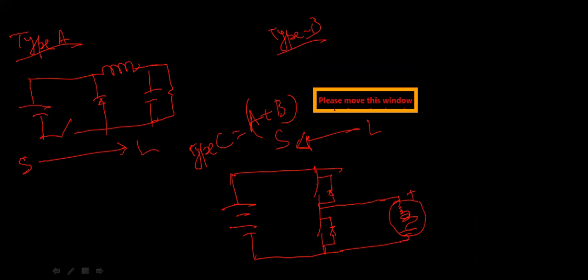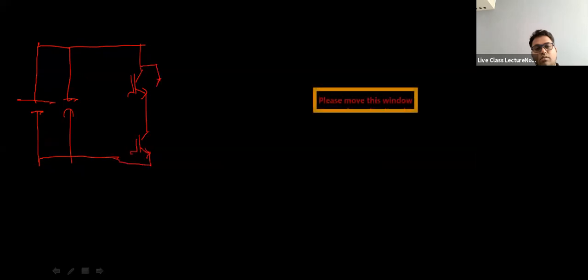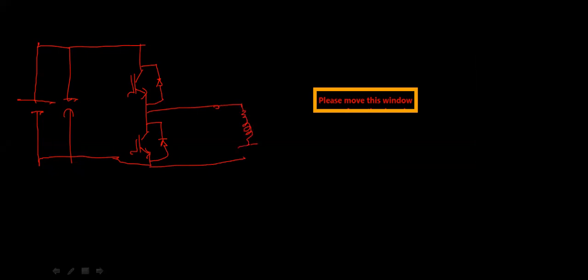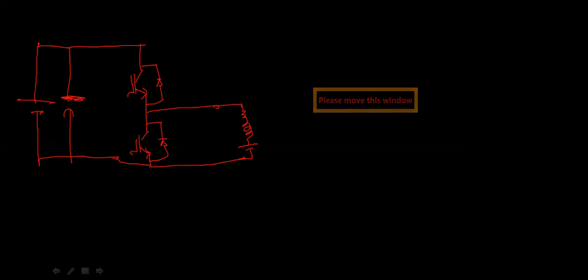We have to give the name of the diode and resistor. First of all, we need to place a capacitor in parallel also, else regenerative braking will not happen. So this is the complete circuit with the IGBT, and the capacitor is there not for protection, but for storing the regenerative energy that will flow back to it, right?